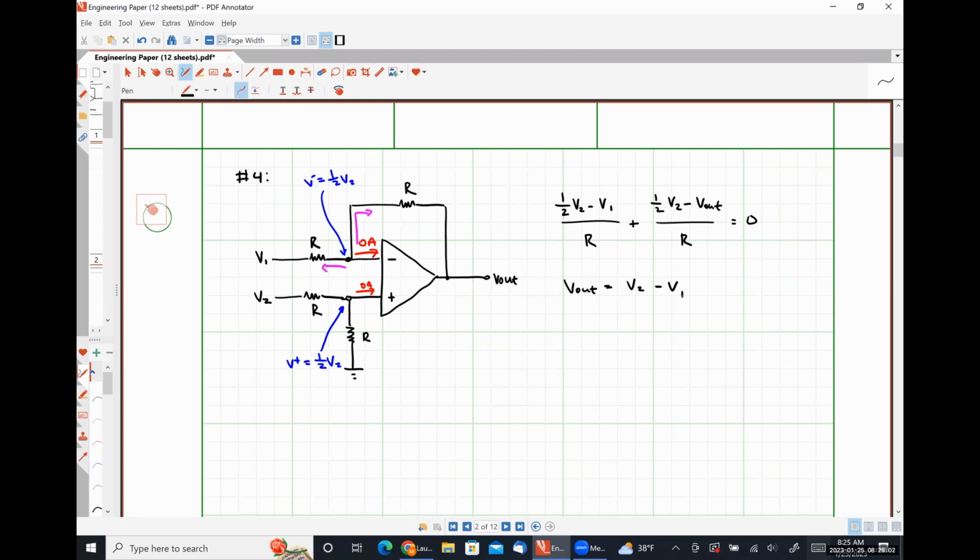So I would argue that if you wanted to do some type of scaled subtraction, your best bet would be to do a two-stage or multi-stage amplifier where the subtraction takes place just doing something like this, and then you could either scale your input signals or scale the overall output by feeding this as the input into another stage. Okay. The math behind weighted differencing is just wildly annoying. It's much easier to just use two circuits to do it. So this is our differencing amplifier.